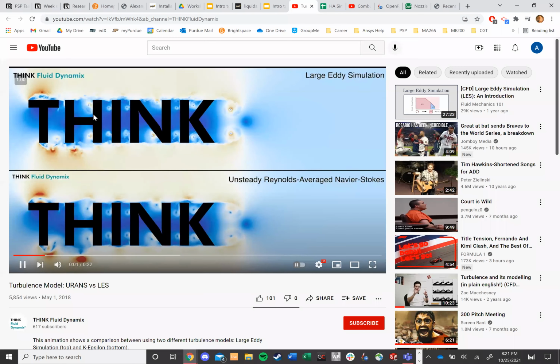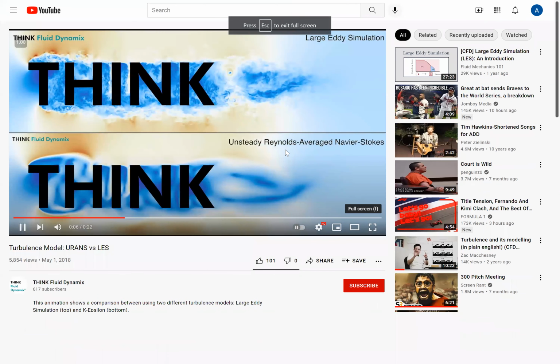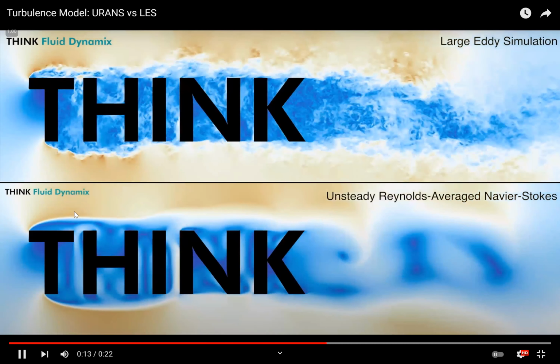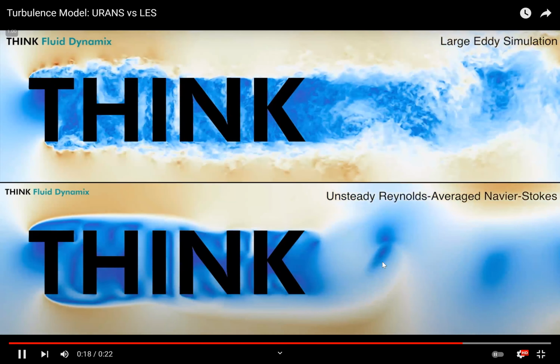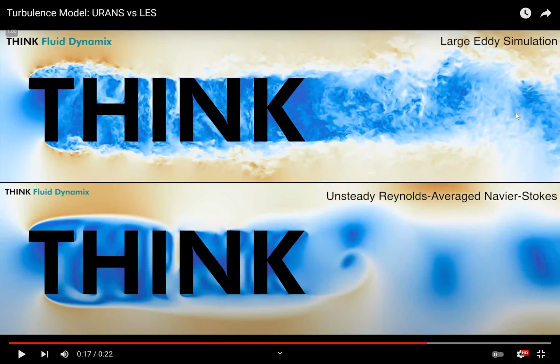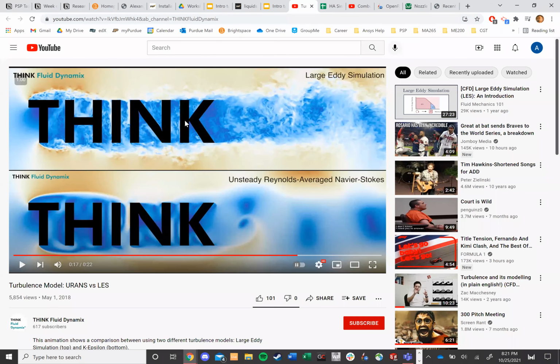This best illustrates the difference. You can see the top is extremely well resolved. There's a lot of detail in the eddies and the smaller whirls. And down here, you can see the bigger picture. It's not exactly inaccurate, it's just less detailed. So that's what you can expect using RANS. And this is what you can expect using LES, which is close to DNS, which is direct numerical simulation, but still modeled. So this is not even as accurate as you can get it. There are longer simulations which can get more accurate here.